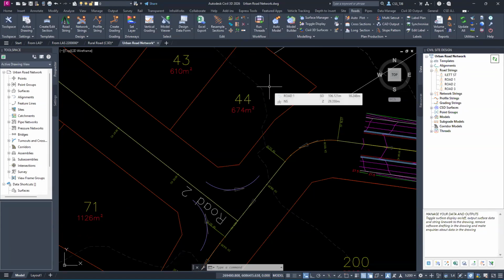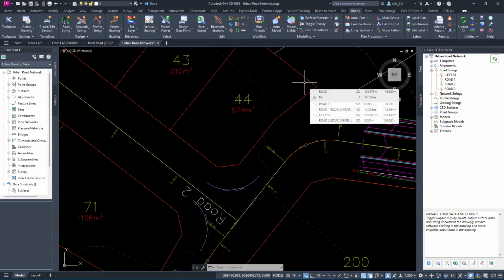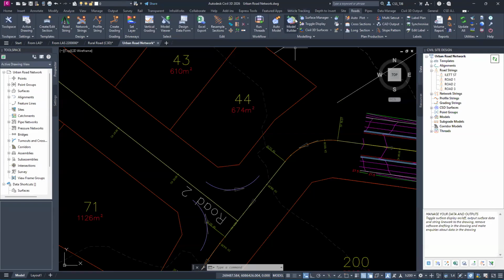There was a question in the chat, which I did answer early on, about in model viewer, can you see the thicknesses of things? No, you can't. Model viewer is just about the top surface. Subgrade model manager would be the way where you'd see the thicknesses of things. But corridor, if you've got Civil 3D, is a way of sharing your model across to a corridor object, which is a Civil 3D road model network, which could be shared out and used for volumes. But the IFC is probably the nicest way to see the thicknesses of things. So I'll do both of those now.